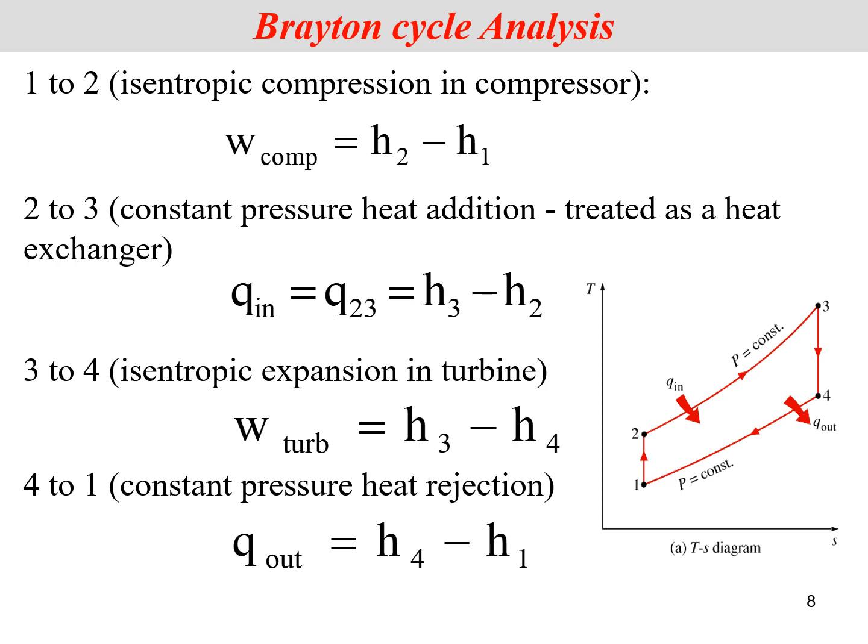You can see, like we solved the steam power plant, we had Q minus W is equal to delta H. Because this is an isentropic process, Q becomes 0, and we have compressive work: minus W out is equal to delta H. Since we have already written compressive here, we can just write plus, and we can say W compressor is equal to delta H.